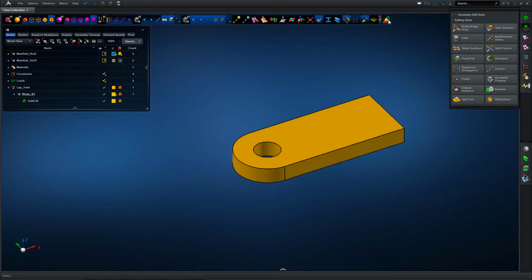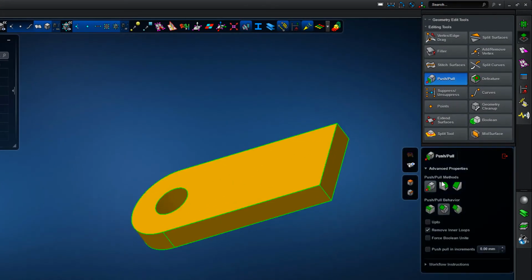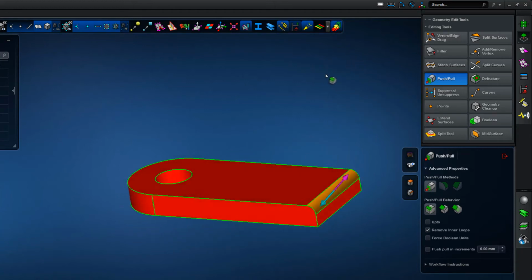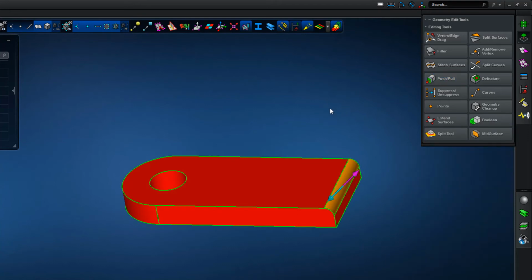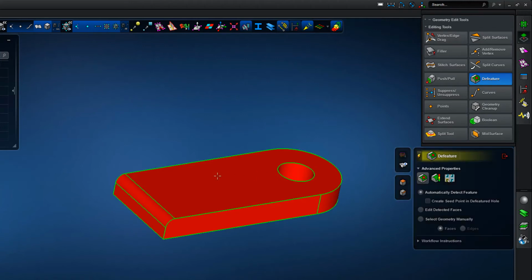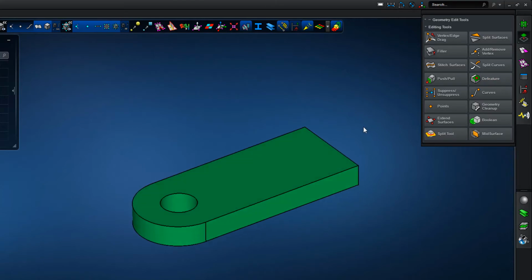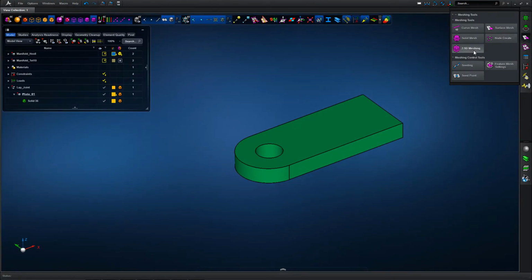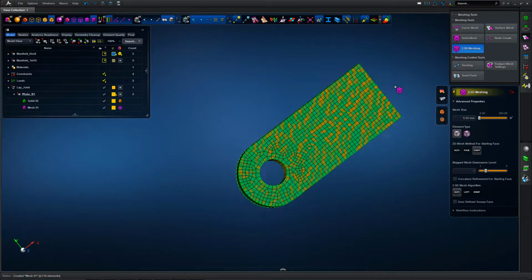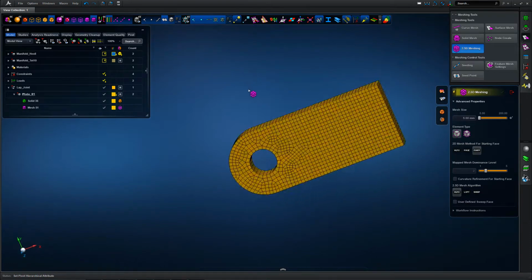So we're just punching a hole through the center of the solid, and again we saw there that the geometry is green when we put the 2.5D mesh type on, and as soon as we put a fillet onto the geometry, so it's no longer mappable geometry, the structure turns red and we can't hex mesh that directly. Defeaturing that solid, simplifying it, goes straight back to green, and we can hex mesh this in 3D if necessary. Going into the 2.5D meshing tools, setting an appropriate element edge length, we can develop the mesh very quickly.